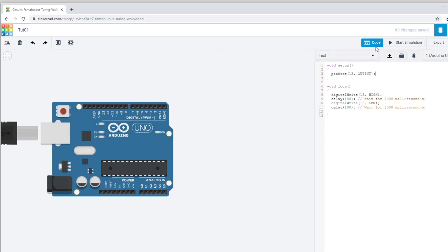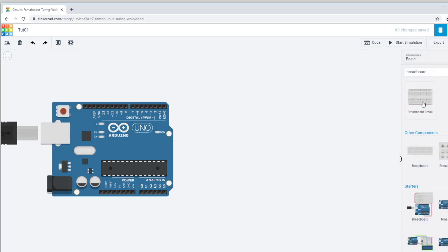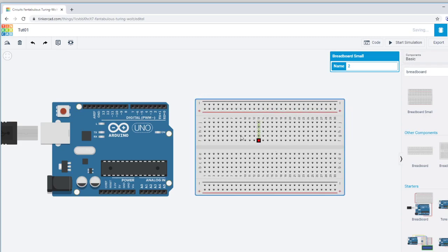So I'm going to drag some breadboard on. So I'm just going to close the window down. I'm going to click on here and look for some breadboard. So click on breadboard. I'm just going to drag the small one across. If you've not used breadboard before, this entire wire is connected, so anything we plug to this will link itself together. Same for the positive rail. Every single pin is connected. On these rails, it's everything up and down is connected. It just makes forming connections much easier than trying to solder things together, again, especially for prototyping.